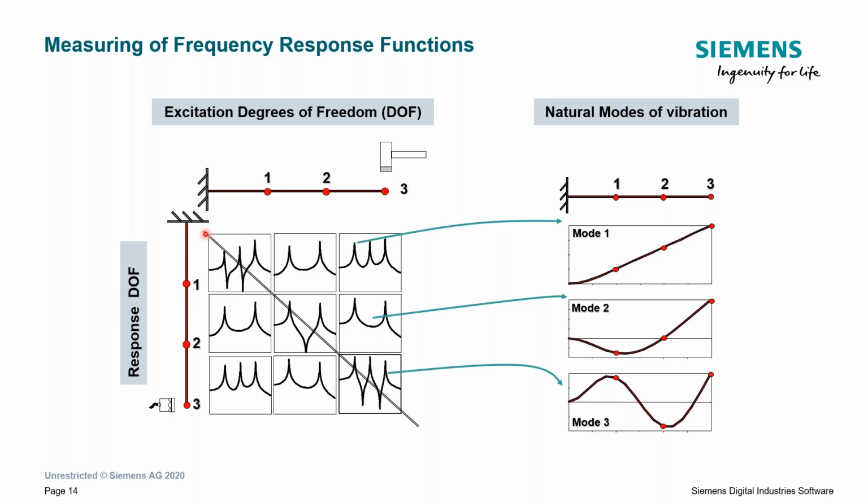And so when I make this matrix, the diagonal of the matrix is going to be my driving points. In other words, I've got hammer hit and accelerometer at location 1, hammer hit and accelerometer at location 2, and hammer hit and accelerometer at location 3. All right. And you can see in terms of driving points, I'm exciting all 3 modes that would correlate to this simple beam.